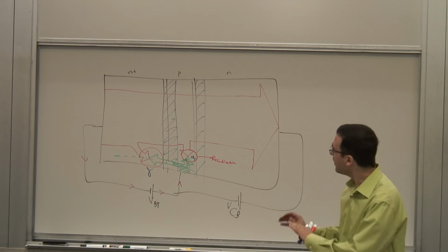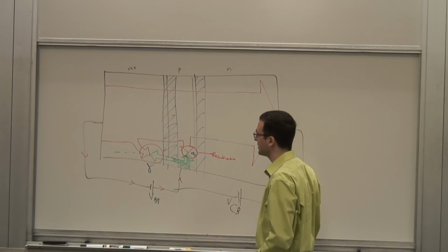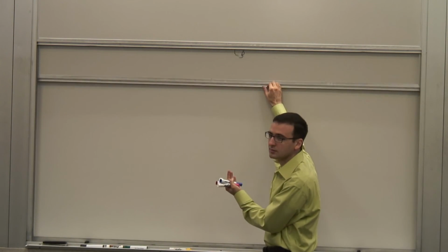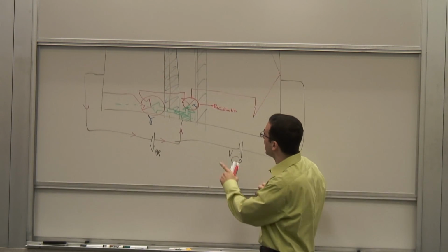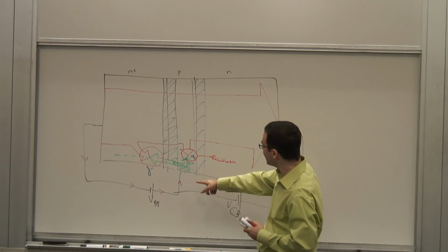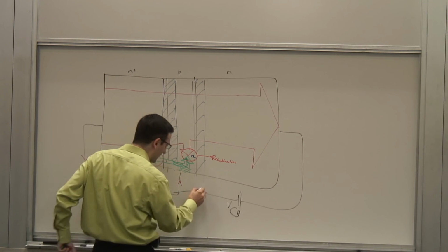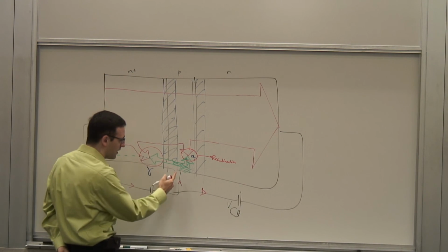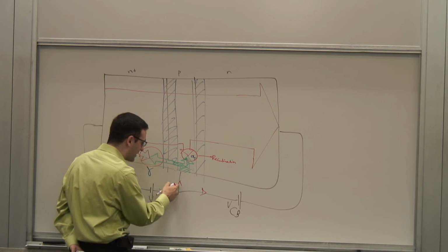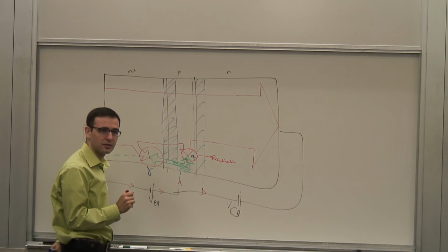Okay, now, note so far, this is the model we have for the transistor, but this is not a circuit model, right? So let's look at the circuit. By the way, I'm sorry, one more thing. You can see here from this picture clearly that the base current in a properly designed transistor is to account for these lost holes, and it should be smaller than the collector and the emitter current, right?